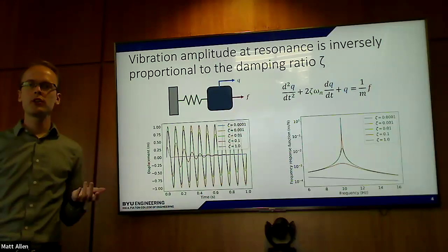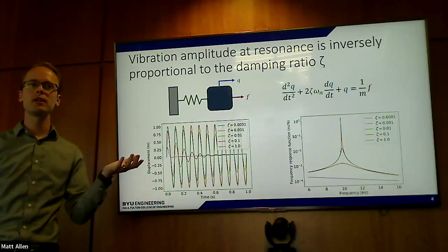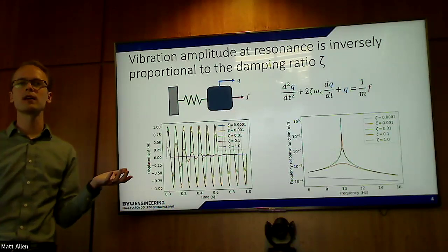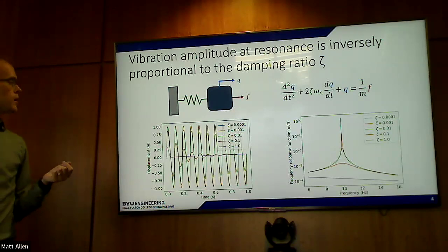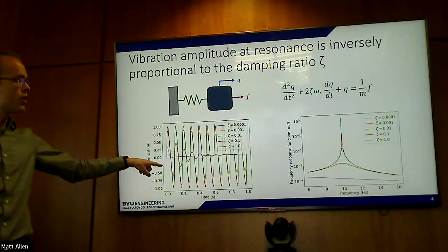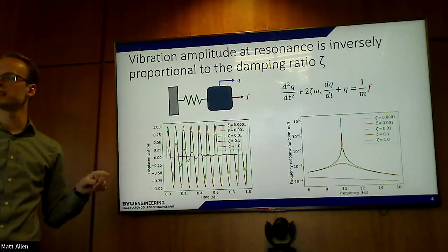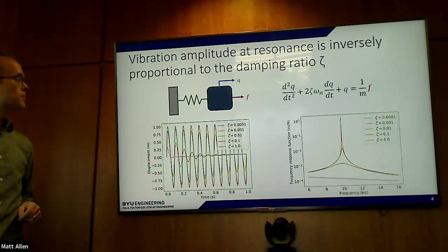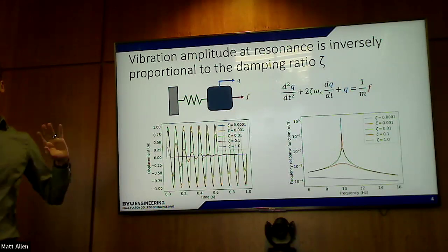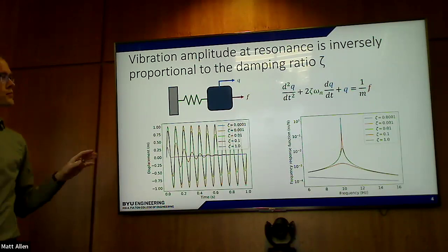And it's called damping ratio because it's a ratio of how much damping do I have relative to critical damping, which when the damping ratio is 1, it's called critical because at that point there's actually no sinusoidal component to the solution and it's purely exponential decay. So you need a damping ratio less than 1 if there's going to be vibration at all.